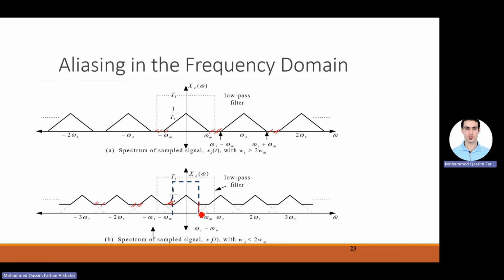That will be the input of your DSP system, while it should be something like this. All right, so that's it about sampling. We will not do a lot of work on this one. You just need to know that you have to sample at least twice the signal frequency.